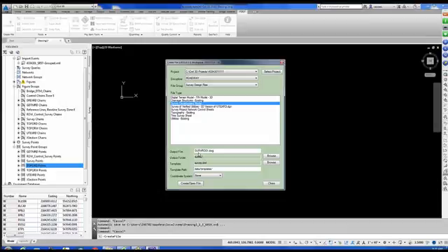If 01 exists, the counter would go to 2 or to 3, depending upon what's in the folder. Now, if someone had gone in, created this file and renamed it to like servrd 10 instead of 01, when we come back into this folder, the software is going to go back to 01. It's not going to start at 10. It's going to go back to 01 and build up, if you did 9 of these, until it would get back to the counter of 10. So just remember that if you rename them externally, then you'll notice there'll be some issues. Don't try to rename the file here. Rename it outside in Windows Explorer.